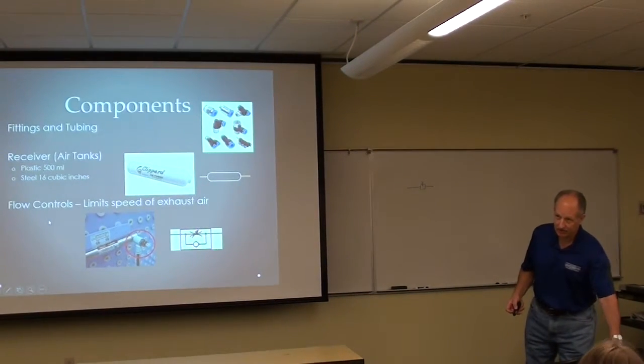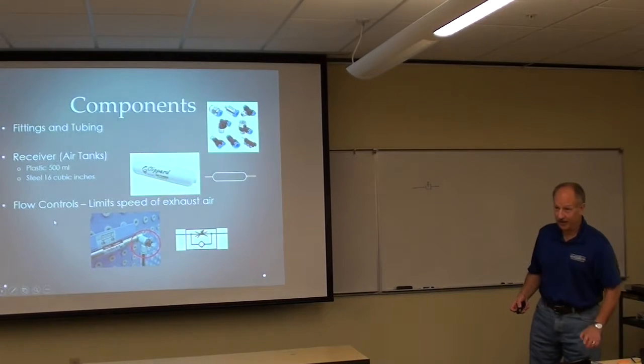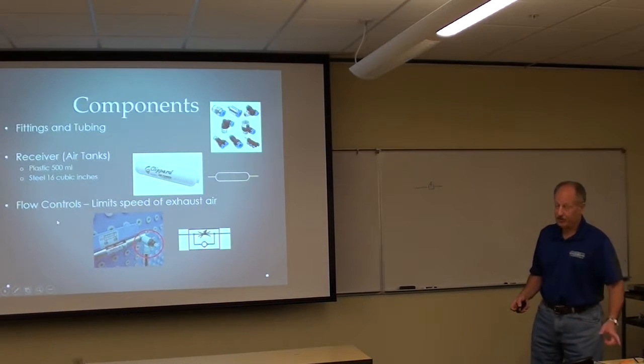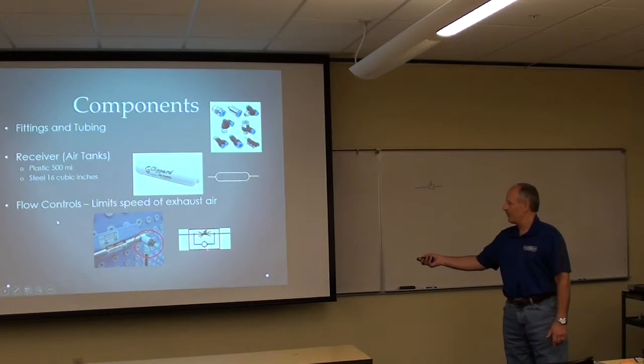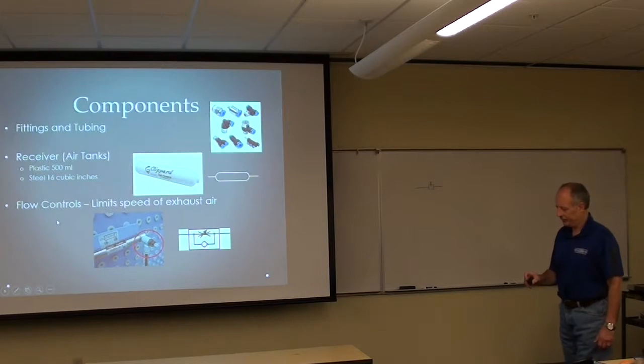It just means that it's controlling flow in the reverse stroke, the other stroke. You have to get one with this check valve in the opposite direction, because when you're pressurizing that side, it goes through the check valve and bypasses the needle valve. So when you're metering, this check valve is closed, and this is the only path for the air to escape.